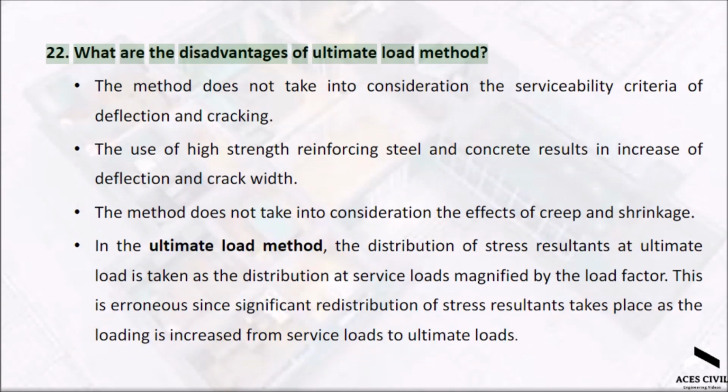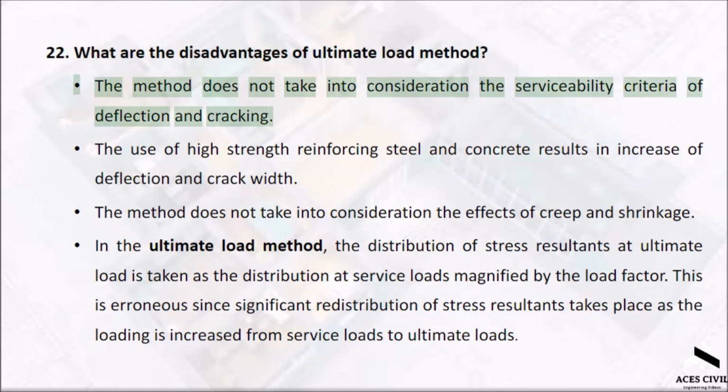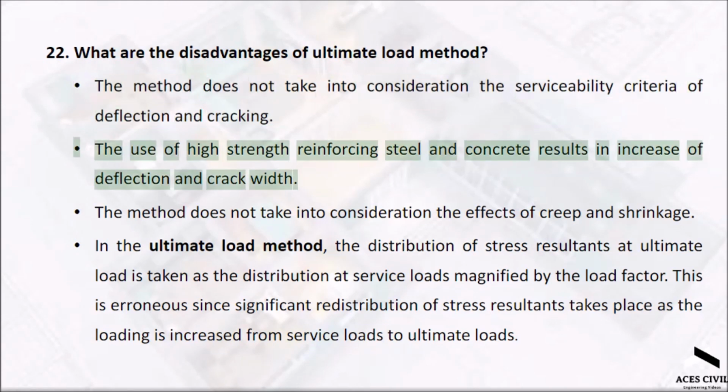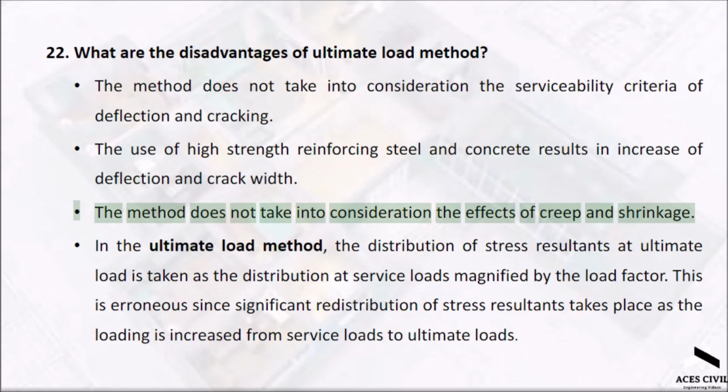What are the disadvantages of ultimate load method? The method does not take into consideration the serviceability criteria of deflection and cracking. The use of high-strength reinforcing steel and concrete results in increase of deflection and crack width. The method does not take into consideration the effects of creep and shrinkage.